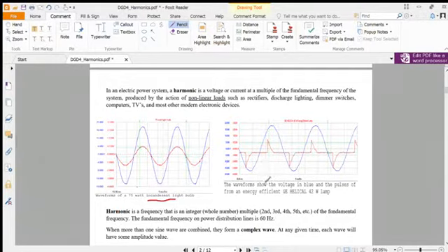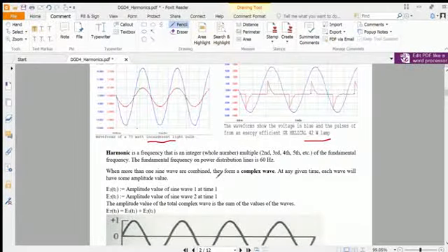But here on the right-hand side is the diagram for the spiral 42-watt lamp. Here the same source supplies a sinusoidal voltage, but we get a distorted current wave. There is a spike here, and a spike here. So this definitely reduces the power quality. Later on we'll show how harmonics affect power quality.